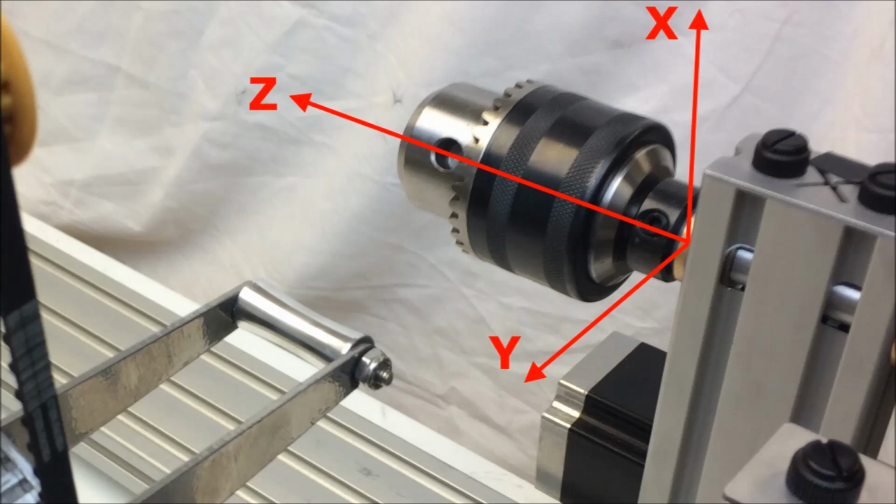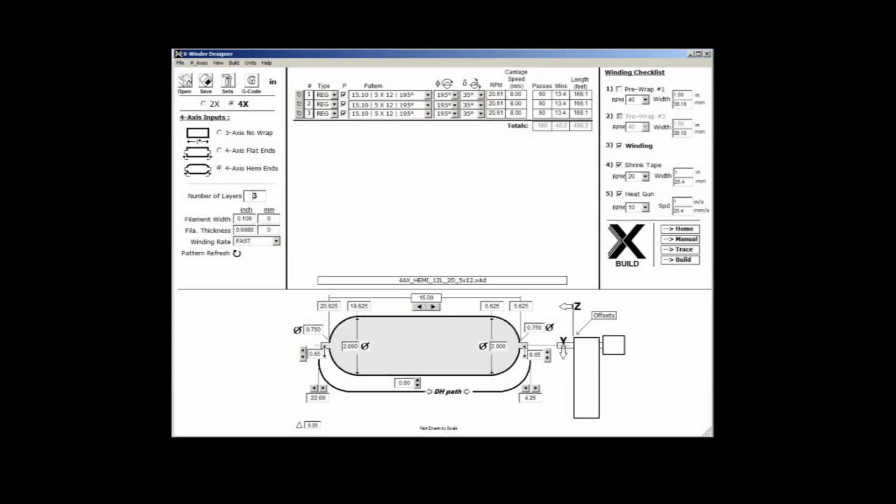This offset defines the origin of the winder's coordinate system, and all mandrel position measurements should be made from the front face of the right mandrel post. Mandrel dimensions. After the mandrel is mounted, measure and input the right end, the right equator, the left equator, and the left end locations. If you are wrapping around a flat-ended mandrel, the equator locations are not necessary.